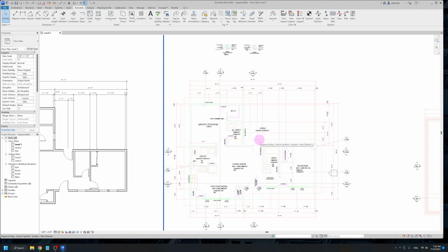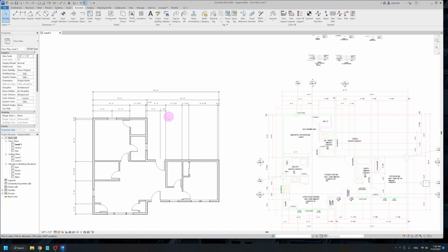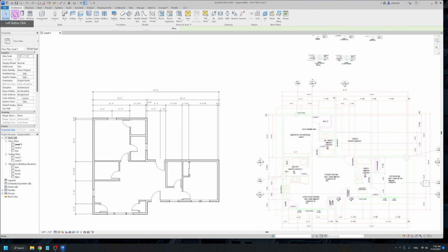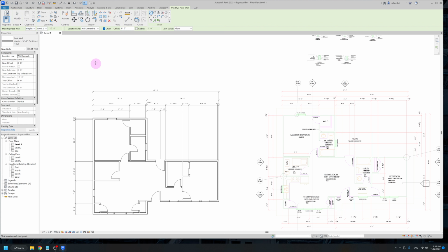You might have a specific square footage that you need to meet, or a specific boundary perimeter that you can't go over, but you're going to be able to make these numbers up as you go, or kind of as you work. So when you're in the architecture tab making your walls, you can have it where you are just drawing your walls based off of core exterior faces, and then just say, I want this to be 30 feet, and it'll just make the wall that's 30 feet.